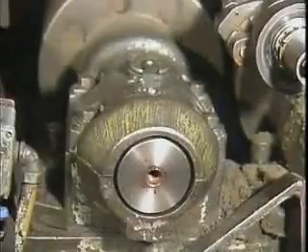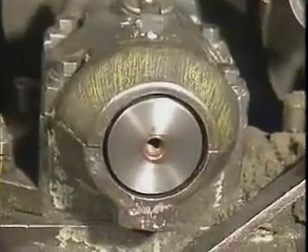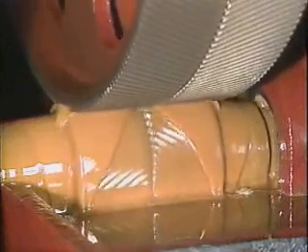Whenever movement takes place between surfaces that are in contact with each other, friction, or resistance to the movement, occurs. Friction between the moving parts of industrial equipment can cause excessive heat and wear. So lubrication is used to help reduce and control friction. Lubrication is the act of applying a substance called a lubricant that creates a slippery barrier between surfaces that would